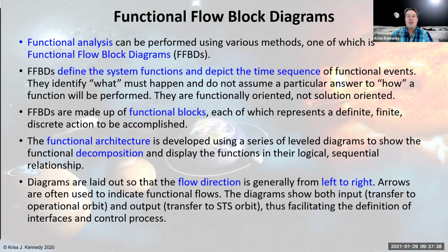Functional flow block diagrams are important to the process because it lays out an understanding of what the functions are. So functional analysis can be performed in a variety of methods, and one of those is this idea of a functional flow block diagram. And I do recommend that is something that you look at and understand and use in your design process before you're even designing your spacecraft or your system. So these FFBDs define the system functions and depict them in a time sequence of functional events.